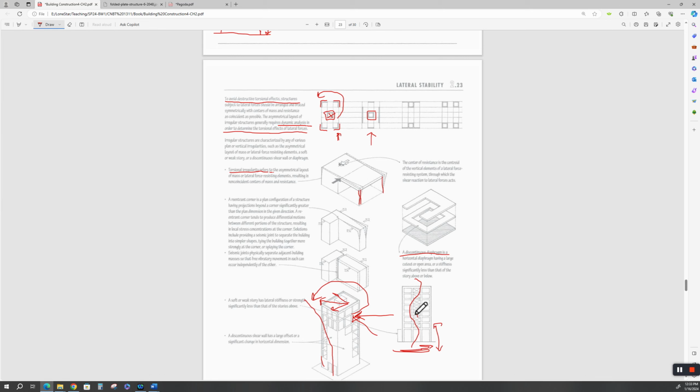Now you see this cross bracing in here, in this view. What is that? Okay, well that looks like K bracing, or it represents shear walls going all the way up the side of that building. Or it could mean what? It could mean those are blockouts. Depends on the drawing. The architect and you're going to have to get together. That tells me that that's not an opening for windows. But that's just from my old days of being a structural engineer.